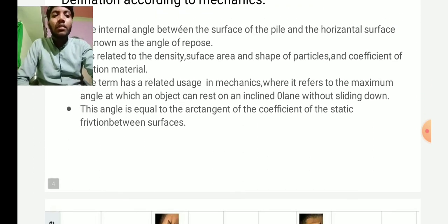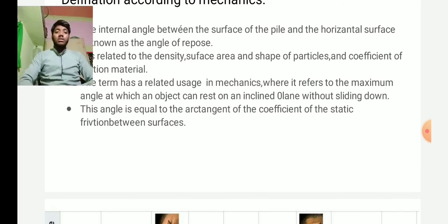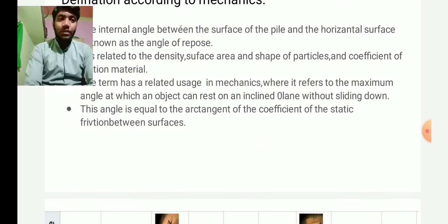The angle of repose is sometimes used in the design of equipment for processing of particulate solids. For example, it may be used to design an appropriate hopper or silo to store the material, or to size a conveyor belt for transporting material. It can also be used in determining whether or not a slope will likely collapse.